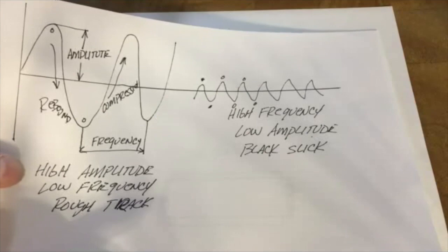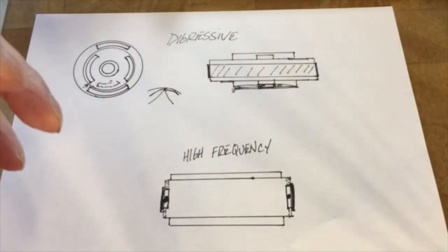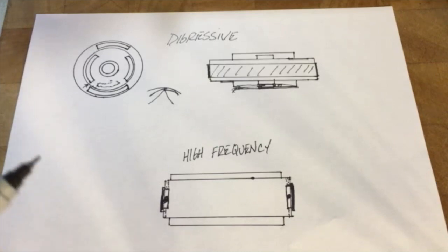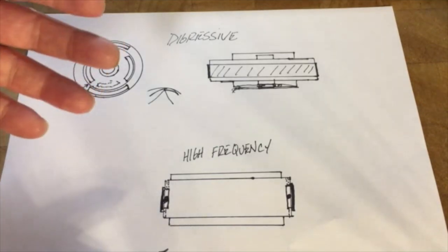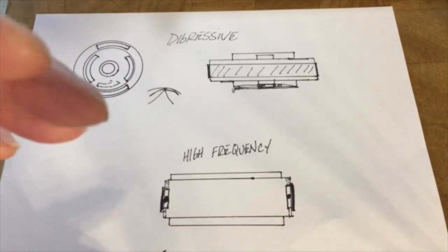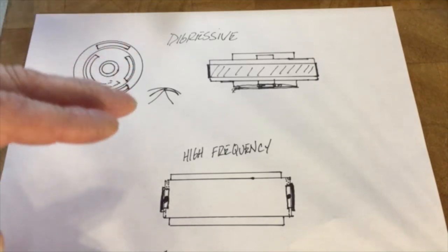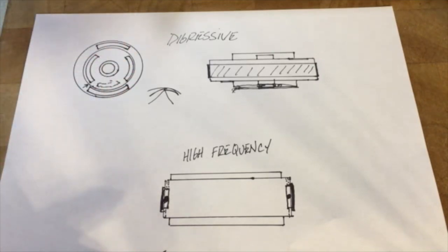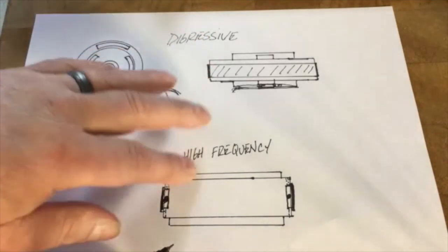Tires are changing directions a lot, and the stretch is coming out of the tire, and it has a potential of losing traction. We learned about this before with tires. Anytime that stretch comes out of a tire, you're giving up a little bit of traction. You always want that tire folded and stretched, and to do all your metering with your shocks.